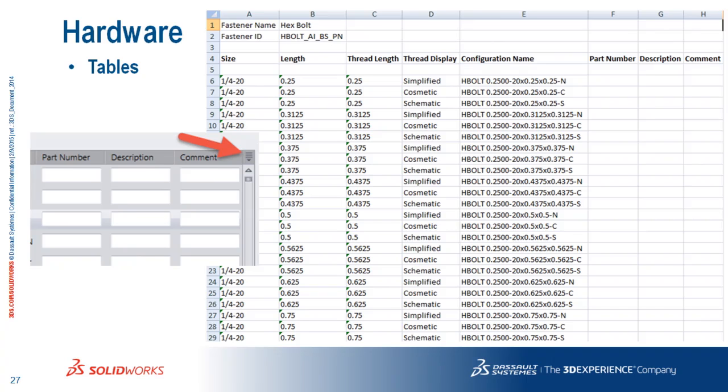Back in 2011 to 2012, they made a change to the toolbox that took all of the fastener data out of the Access database and left only the Hole Wizard data in there. What they did with that toolbox data was push it into the file header of the actual part files. They did this for two reasons. One was that it worked better with ePDM if it was in the part, because then you're only accessing one database and not two.